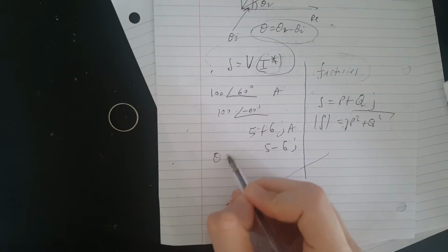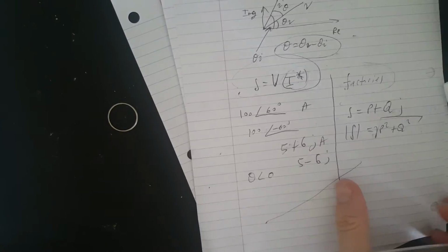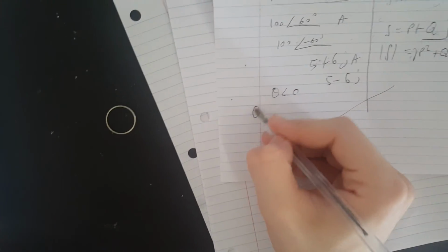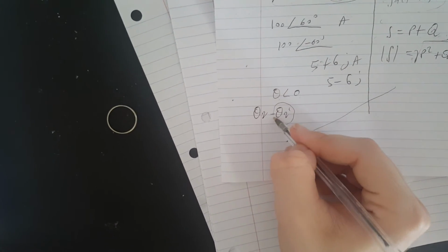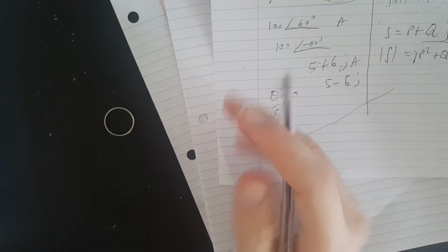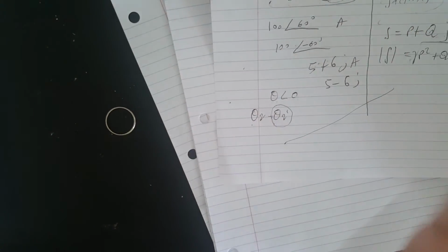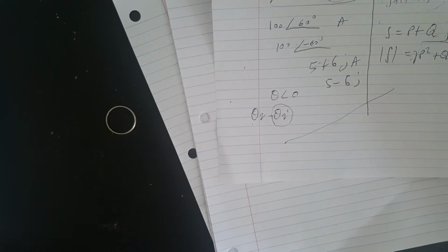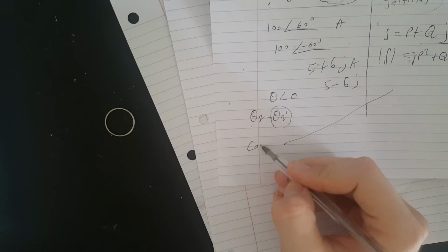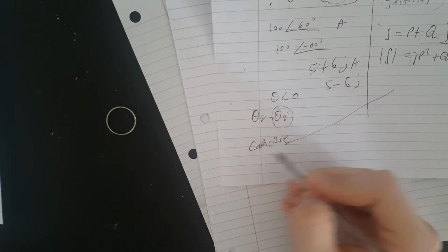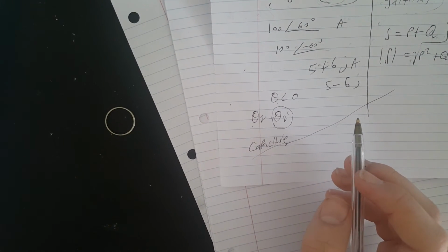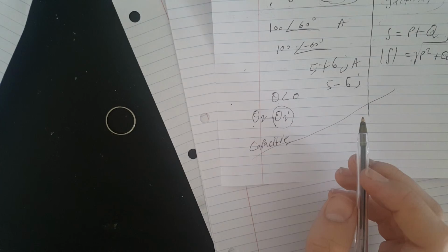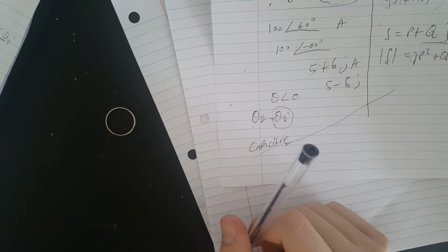You know that when theta is less than 0, what does that mean? Theta is theta V minus theta I. So if theta is less than 0, that means that the current angle is more than the voltage angle, which means it's shifted more to the right, which means that the current is lagging. If the current is lagging, that means that the voltage is leading. If the voltage is leading, that is capacitive. That's just another thing that they emphasize in this section, and that's pretty much it for this section. Pretty quick video. That's all I got.